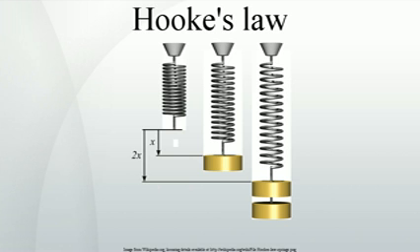General scalar springs. Hooke's spring law usually applies to any elastic object, of arbitrary complexity, as long as both the deformation and the stress can be expressed by a single number that can be both positive and negative. For example, when a block of rubber attached to two parallel plates is deformed by shearing, rather than stretching or compression, the shearing force and the sideways displacement of the plates obey Hooke's law, for small enough deformations.